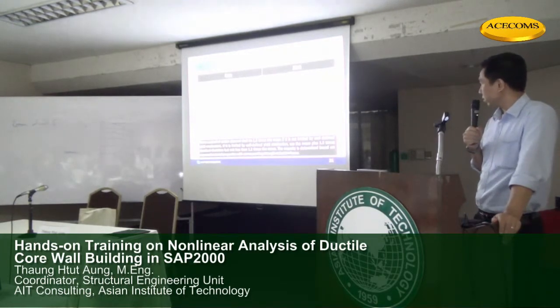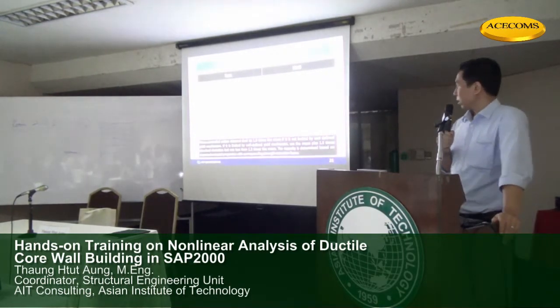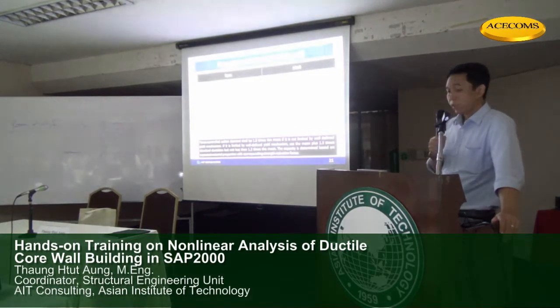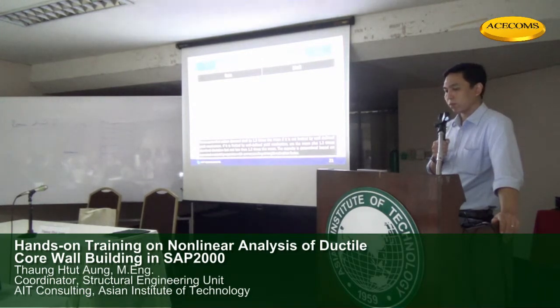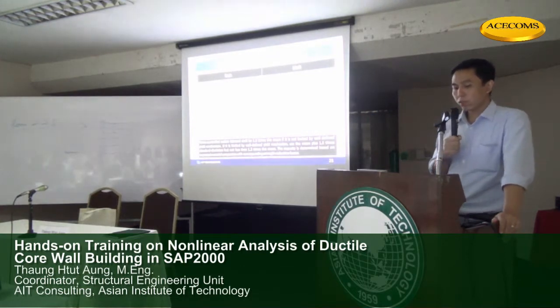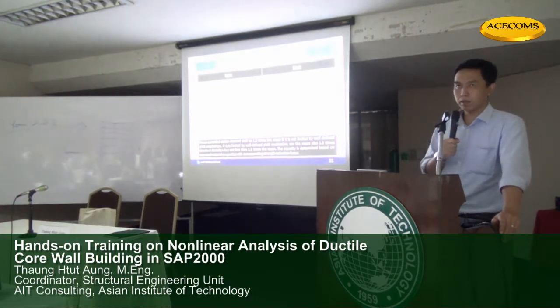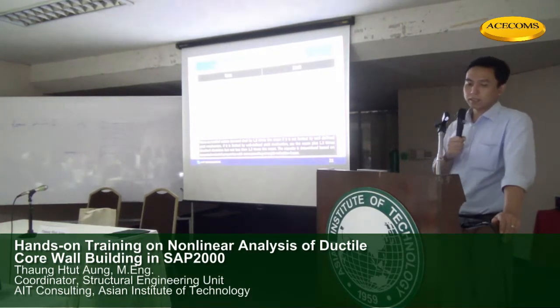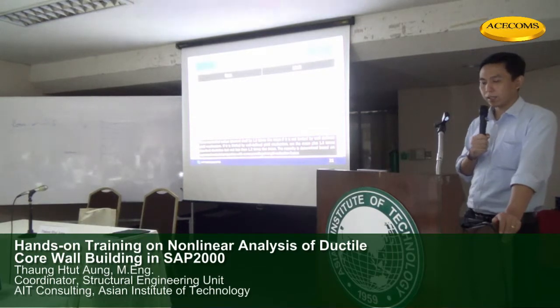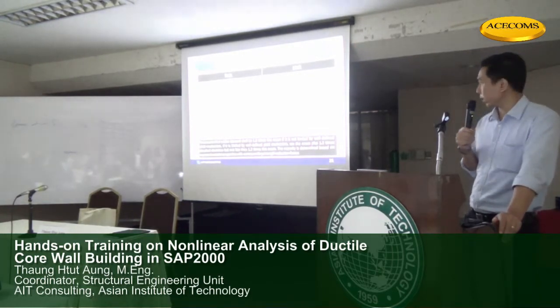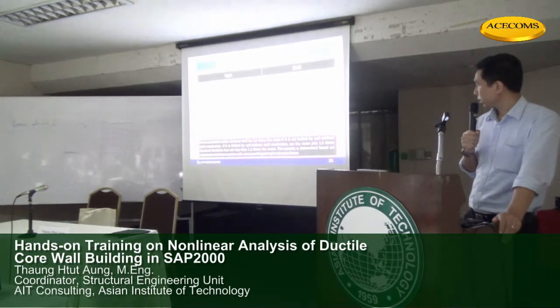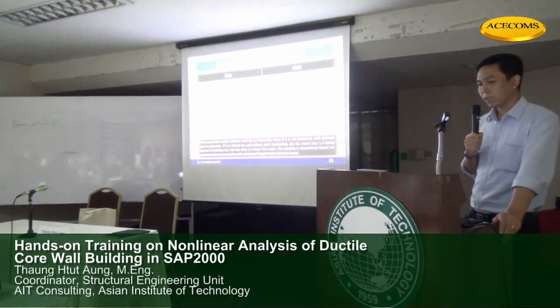So in the load combination, we have to increase the load for the frame, but that 10% of base shear attracted by the frame is not uniform throughout the height of the building. At the upper floors, the shear wall will take more force because of the shear wall and frame interaction behavior. The frame is deforming like a shear deformation, but the shear wall is deforming as a cantilever column.